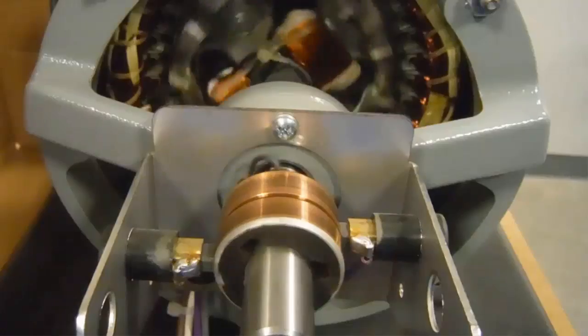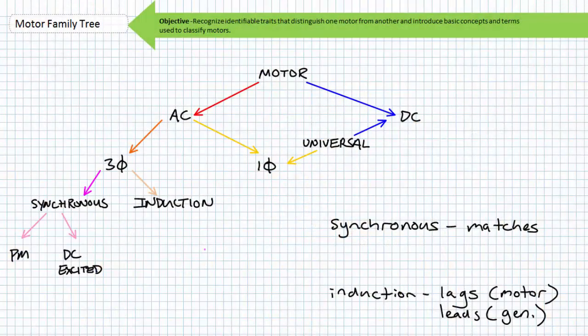This structure is not confined exclusively to the electrical world either. Hydraulic energy is transferred between rotating members and stationary members using a hydraulic rotational coupling. In contrast to their electrical relatives, these are leaky, nasty, messy things that you cannot come away from not covered in oil. Most rotating hydraulic unions include numerous dynamic seals and a case drain to account for this leakage, but that just gets the big stuff.